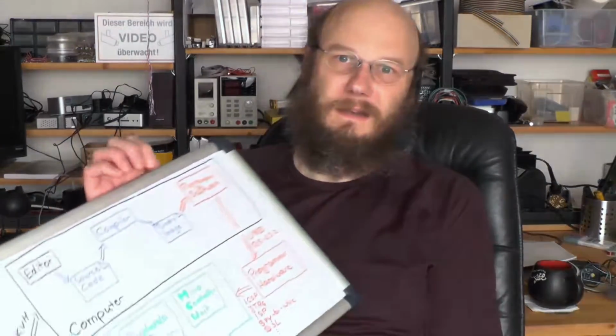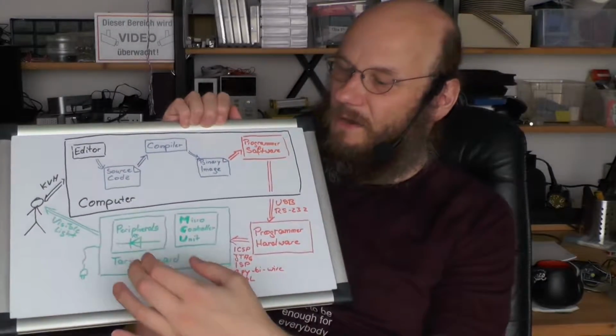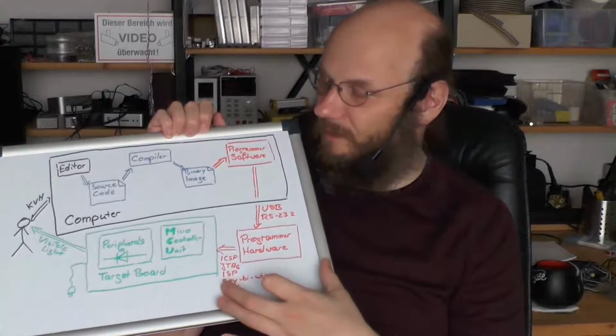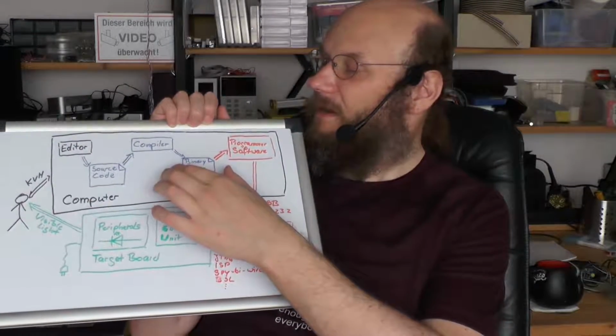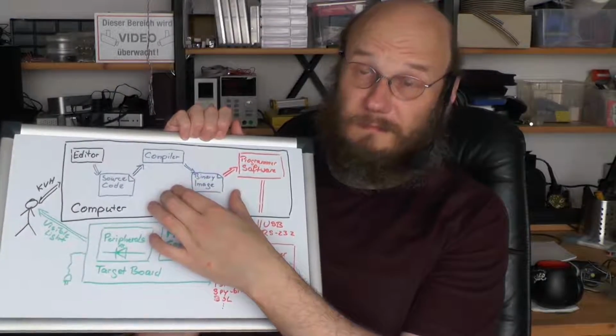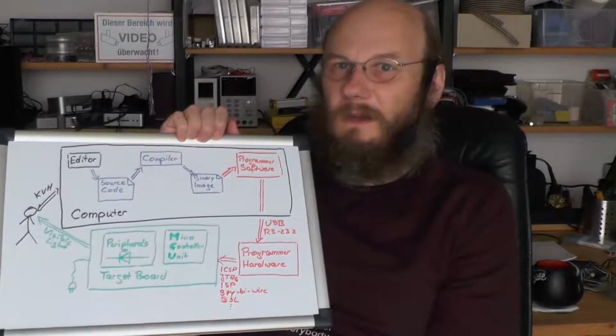Hi folks, today's episode in the microcontroller tutorial series is taking care of the one component still missing in our entire tool chain. We've taken care of the target boards, and at least preliminarily of the programmers and the programmer software, and now it's replacing the binary images we've got from the forum with something we compiled ourselves using a compiler. It isn't rocket science, but involves something that apparently quite a few people are kind of scared of when they just hear the word. It means basically cross-compiling.